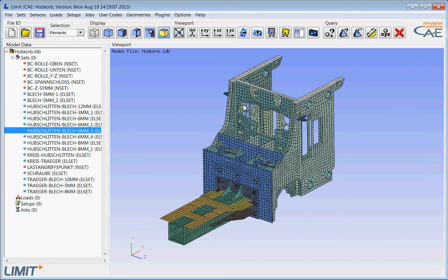One is a global approach where we use the stresses calculated on the bottom and top side of the shells, and we compare these stresses to the permissible stresses given in different codes. So this is the global approach, where we don't really calculate the stresses in the local welds and fillet dimensions.